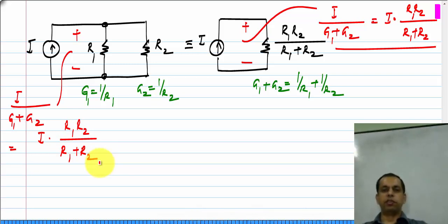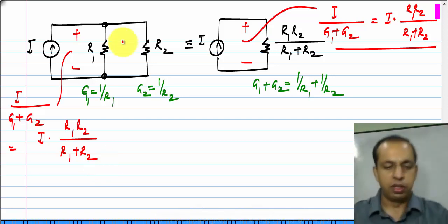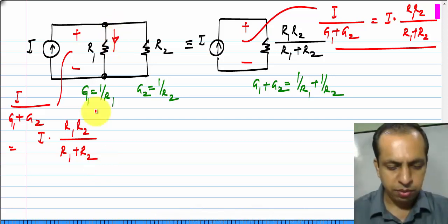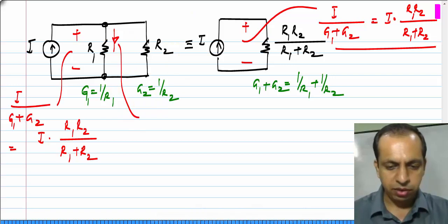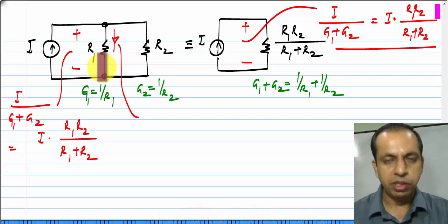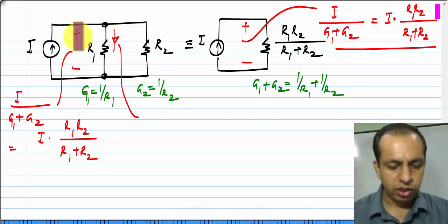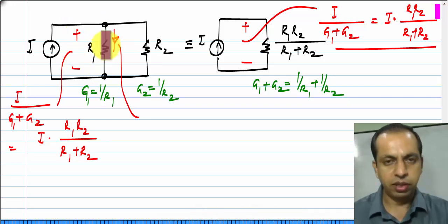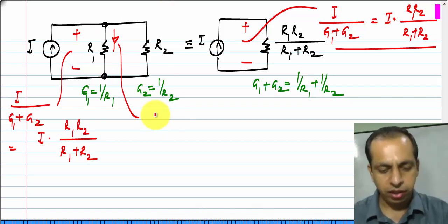Now, you may be asked for this voltage, in which case we have already solved for it, or you could be asked for currents in individual resistors. So, this current is nothing but the voltage across this resistance divided by the resistance, or the voltage across this resistance times the conductance value. Okay, I will write it in both forms.